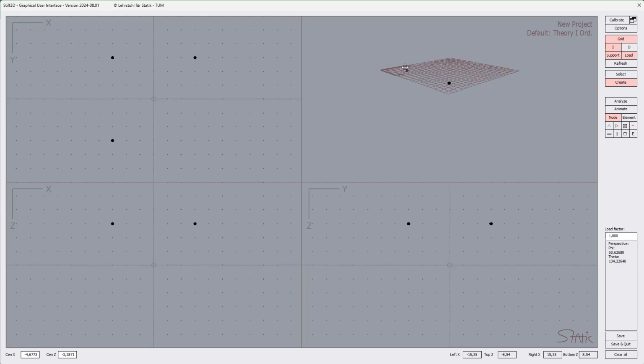What is still missing is the foundation node for the vertical column here at the top left, running to the bottom with the coordinates x to -3, y to -3 and z to plus 3. Somewhere there. No, not this one here. So we come here to x with the -3, that it should be 3 now. Checking x is okay, world y should also be -3, and voila, we now have generated all four nodes at the specific positions that we like to have them.